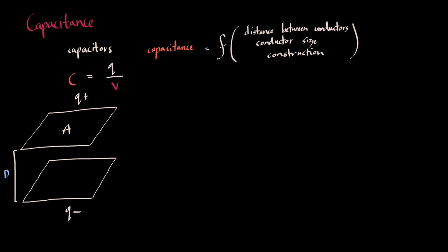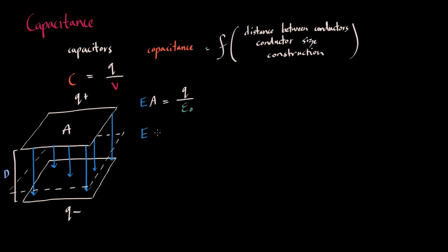In order to find this capacitor's capacitance, we must determine its voltage in terms of its geometry. We can start, as with the spherical example, by finding the electric field within this capacitor by placing a Gaussian surface between the plates and setting up our equations.